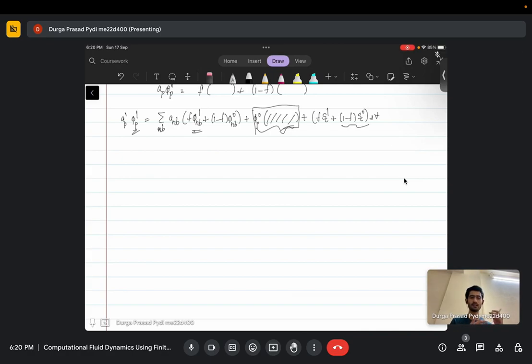Okay. So the next problem is with respect to experimental results when you want to compare. When you are using unstructured meshes, you have better control over your mesh, so you can better approximate your geometry. If your problem is more dependent on your geometry, say you have some aerofoil kind of shape, and you use an orthogonal structured mesh, you will end up with these discrete steps. So your geometry will be different from the actual geometry. If the problem depends more on the geometry, an unstructured mesh will be able to handle that.